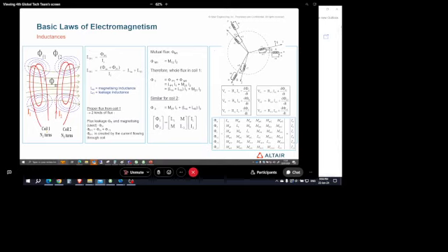If I supply coil 1 by I1, I will produce a main magnetic flux. And I will have this blue magnetic flux, which is the leakage magnetic flux. So the inductance of this coil is phi p, the principal magnetic flux, divided by the current supplied. This is only if I supply coil 1, right? And this principal magnetic flux is equal to the main magnetic flux I created plus the leakage magnetic flux.